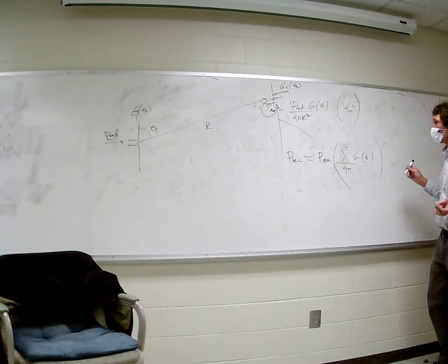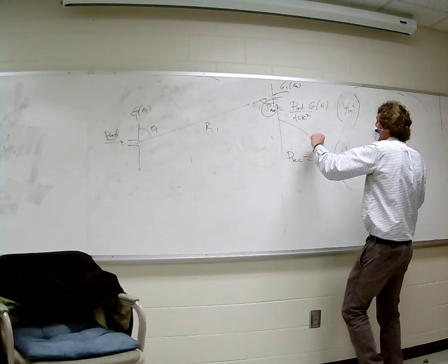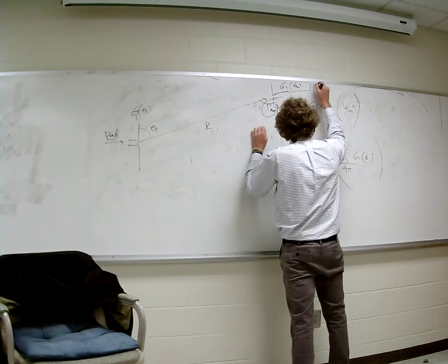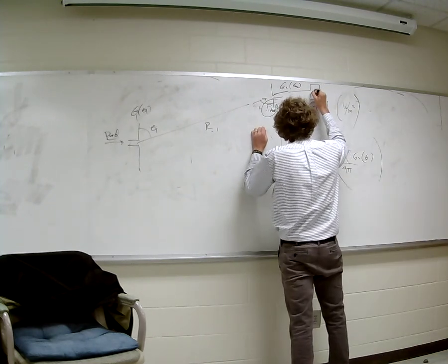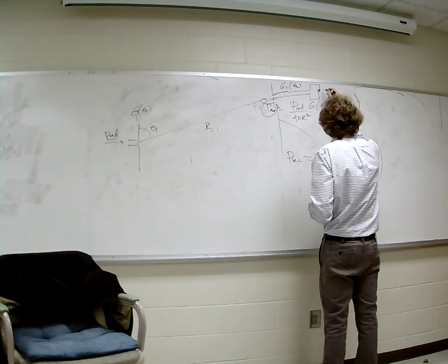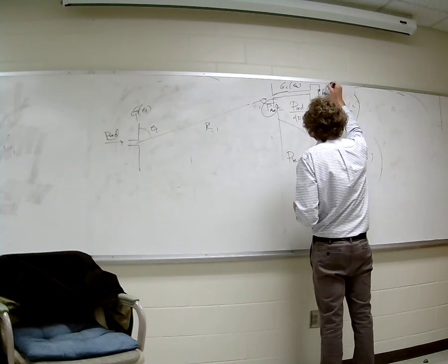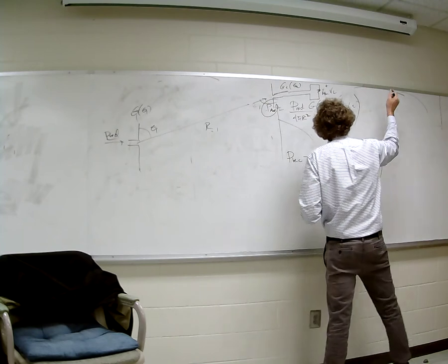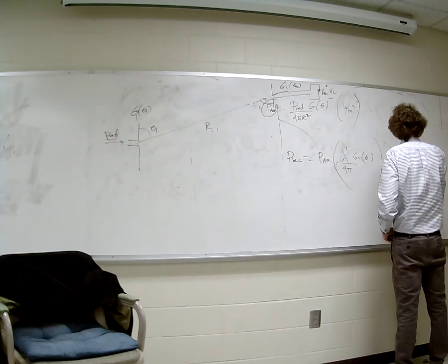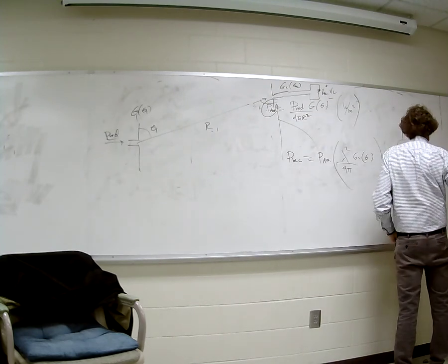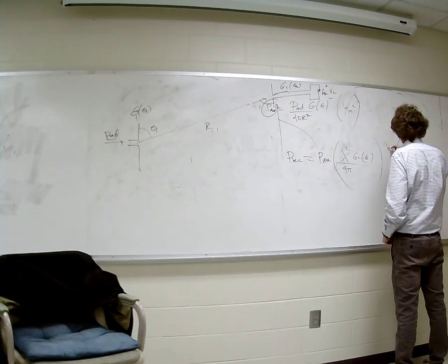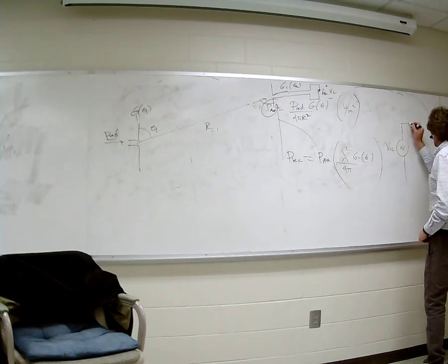What do we need to do? Well, if we had a load on this thing, and this is a cruddy drawing, our load, and we wanted to find the voltage, V load, and the current there. What we need to do is to get an equivalent circuit. That's what part of the thing is. So then we get the open circuit voltage.